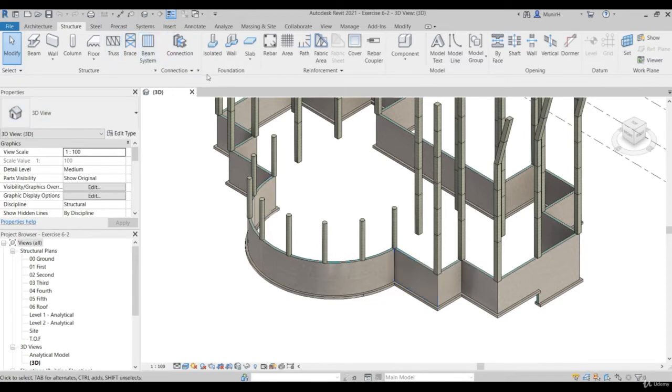So the only trick that we will do is we will make the same isolated footing, but with a big height. In these cases it will be 4,500, the difference between the ground floor and the top of the footing levels. And sometimes we'll go beyond that with 6,500 in order to cover the distance for the weak soil, if you recall the previous videos that we did.